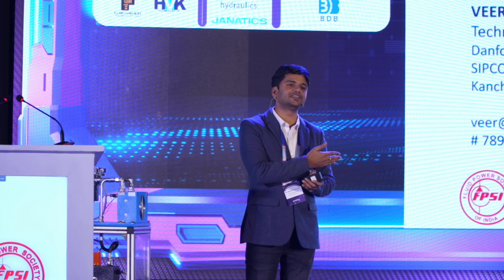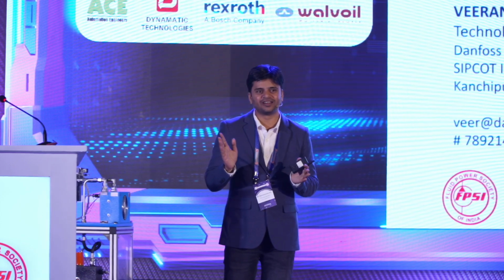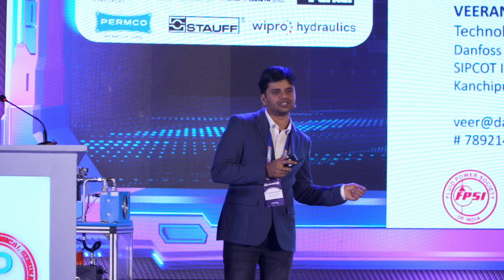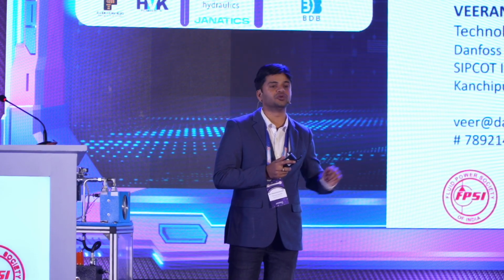In our case, everything is taken care of by filters. And when you go and inspect our customers, most of the pump failures happen not because of our pump, but because of the way they are handling the filters. If there are abrasive particles getting in, and they are not careful enough to install the filter upstream of their pump, then it is going to hurt our pump.